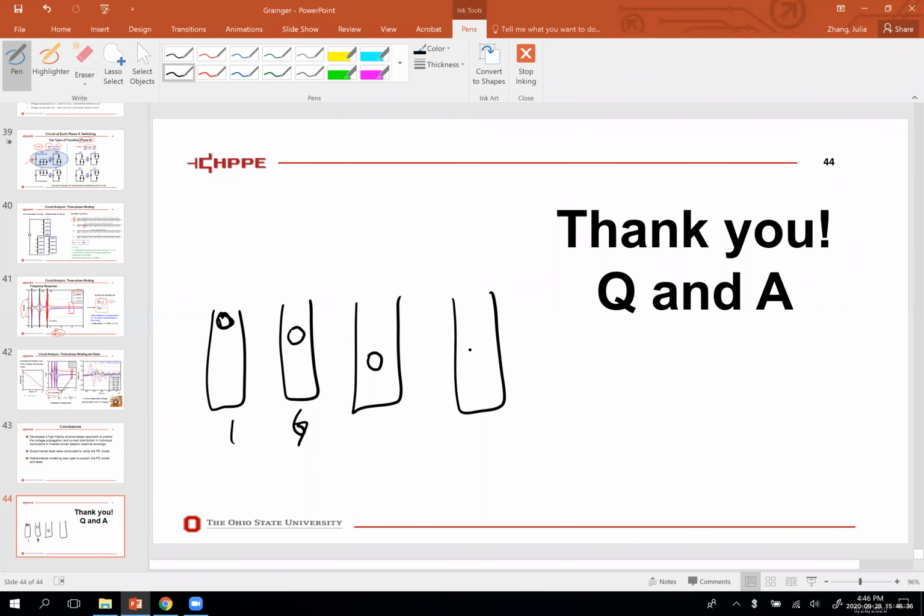Okay, so in general, just like Litz wire and other things, you would want a given conductor to basically occupy all possible positions and give it as much variety as possible. Yes. That's also what all the bar wound wave winding motors do.